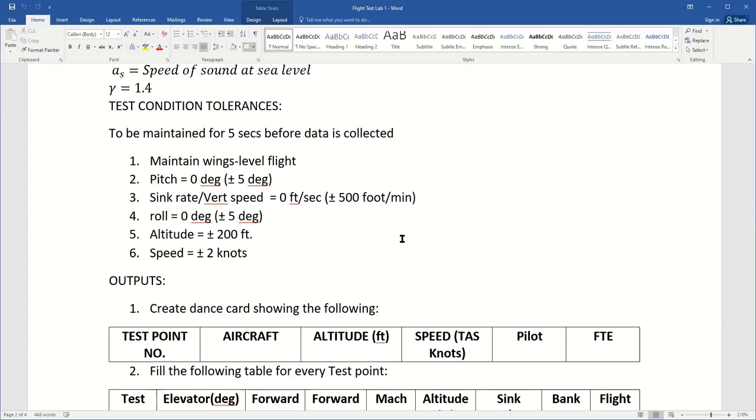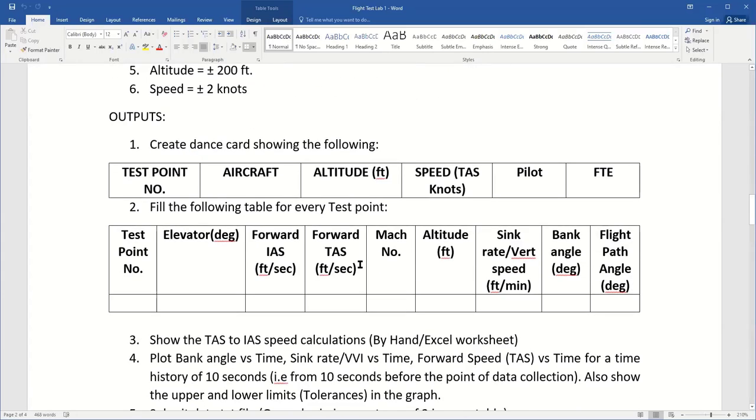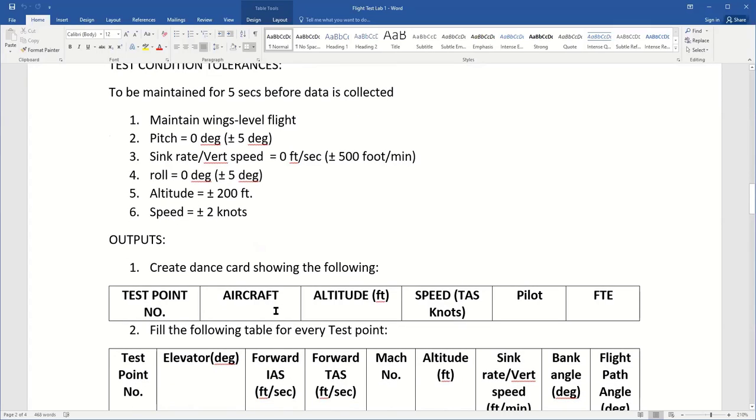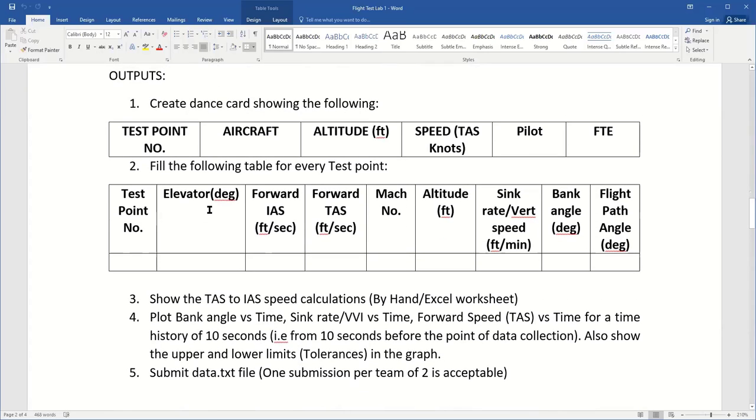Okay. Do they take the target airspeeds and convert them to indicated? Yes. And fly those? Yes, sir. The thing is, you never fly true airspeed. When the data is reduced, they convert all the indicated airspeed to true airspeed, and then they do all the calculations. But a pilot always flies indicated. So they'll be flying indicated, but I'm giving them true airspeed. When you say 250, you want them to fly 250 indicated? No, 250 true, so they need to convert it into indicated and then fly that. Yes, sir. And I've also given them the equations to do the conversion. Fine, I just wanted to make sure they were converting it before they fly.